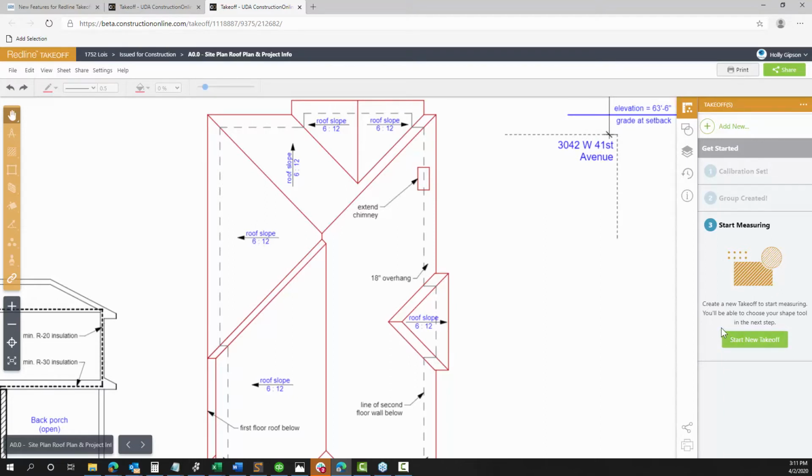Yeah, one thing that the groups really play a role in as well is how that data is exported. So usually I tell people, think about how you want your end results or your report to look when you export your takeoffs out, because the group structure that you create is really going to guide what your report looks like. So there's no right or wrong way to do it, but most people I talk to do have a certain way that they like to group things. An easy path to follow is to create those groups based on how you would normally do your estimate, so that everything's organized, and when it's time to put together some of that costing information, you have it already laid out in the same way that you would for your estimate.